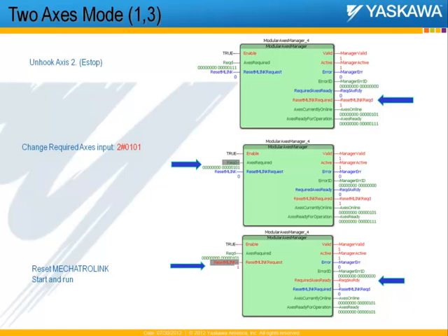And by offline, we do not mean unhooking the Mechatrolink network. We do not expect users to remove or add the Mechatrolink cable to take an axis offline. We're just referring to taking off power or e-stopping a particular axis. Remember, Mechatrolink has to be connected for any kind of communication. If the Mechatrolink cable is removed from one of the middle axes, it will basically cause disruption in communication, and none of the following axes would be able to operate.